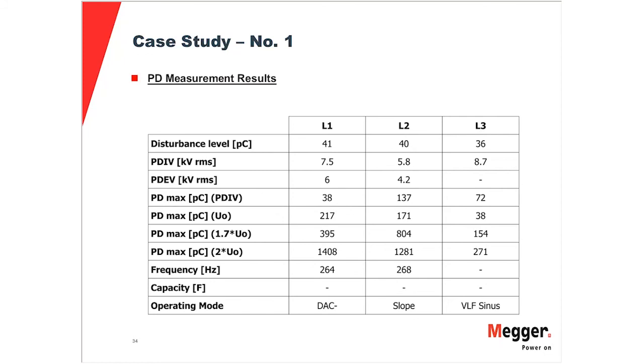I'm not saying that the VLF sinusoidal is bad, it's just the technology which does not allow you to see the faults. Remember, VLF sinusoidal, we are using it ourselves, but we recommend to use it for Tan delta and not for partial discharge, and that is for good reason, because if you invest your time and your money in doing preventive maintenance, you want to make sure that this preventive maintenance is giving you data which is reflecting the reality. And here we clearly see that it is not the case with all test methods.